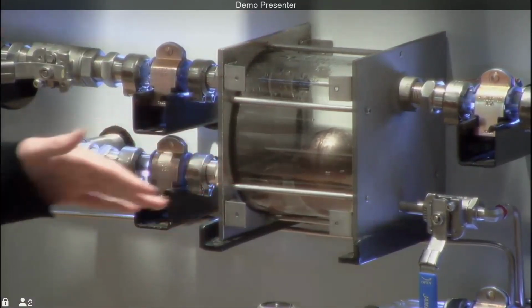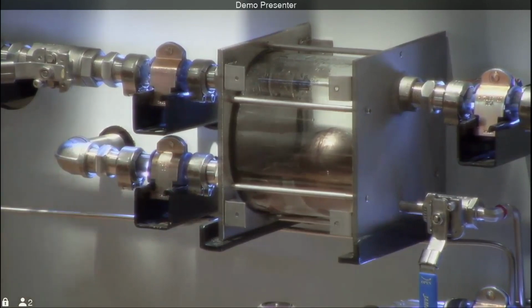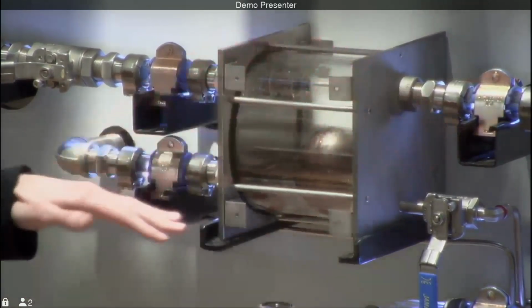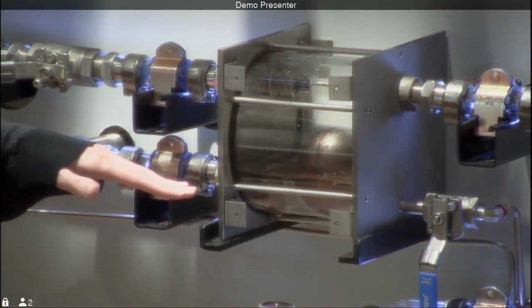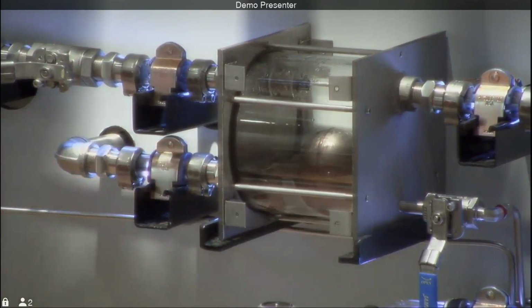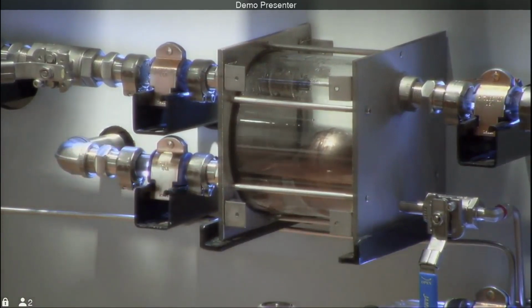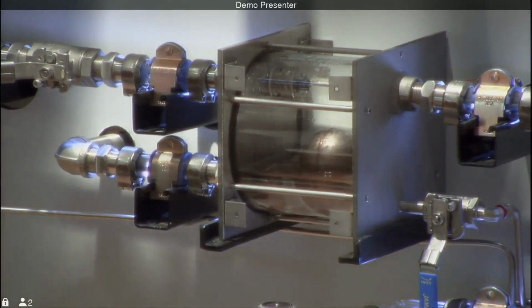They're also a continuous drainer, so they don't have a regular cycle. So essentially, condensate is just going to come in and go right out. And that's important to know that they are a continuous drainer. If you're ever in the field testing them, or if you're trying to troubleshoot them, it's important to know that.